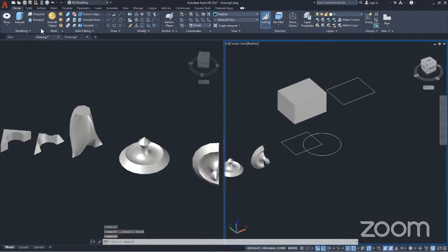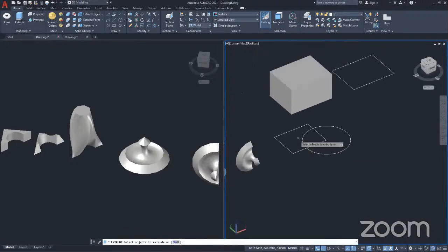Like I said, with the extrude command, if you want to bring up any of these shapes, like let's say we have 3 shapes here, we have this part, this part, and this part, you cannot achieve that with extrude. You need to draw this shape separately, and this other shape separately, and this last shape separately. Then you can press pull them by selecting the lines, because you cannot select any of this part. Don't worry, it will work properly.